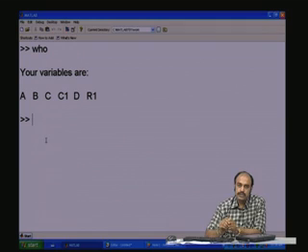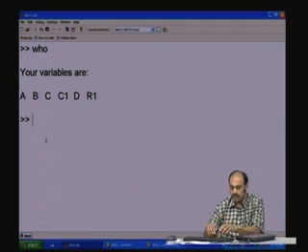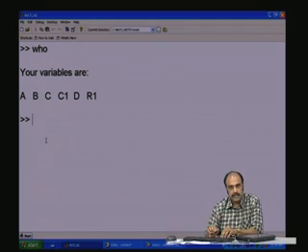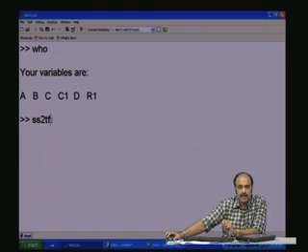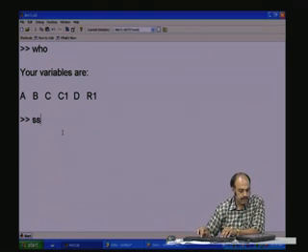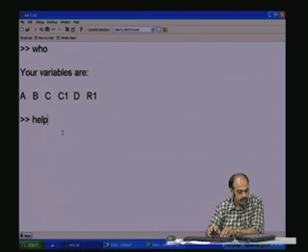So, we use one function in MATLAB called state space to transfer function form, that is SS to TF. So, this means state space to transfer function form. The syntax is very simple. In fact, MATLAB is very friendly. If you want to know the syntax of this, you just have to type help SS to TF.